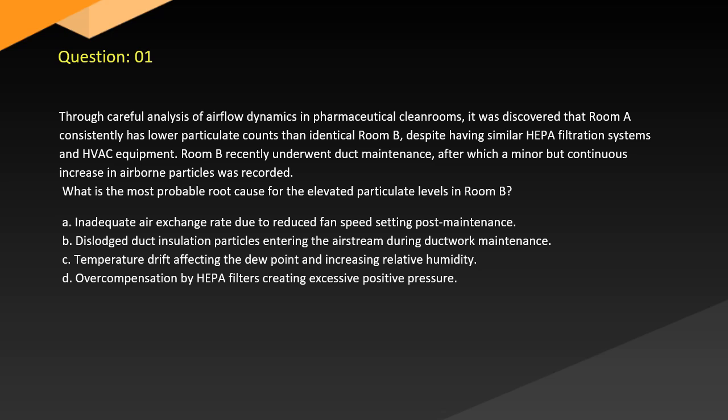Question 1. Through careful analysis of airflow dynamics in pharmaceutical cleanrooms, it was discovered that room A consistently has lower particulate counts than identical room B, despite having similar HEPA filtration systems and HVAC equipment. Room B recently underwent duct maintenance, after which a minor but continuous increase in airborne particles was recorded. What is the most probable root cause for the elevated particulate levels in room B?